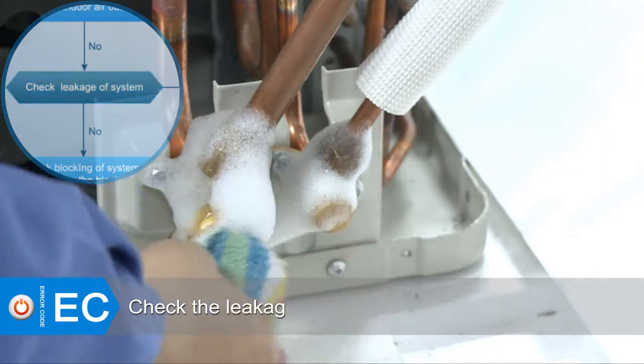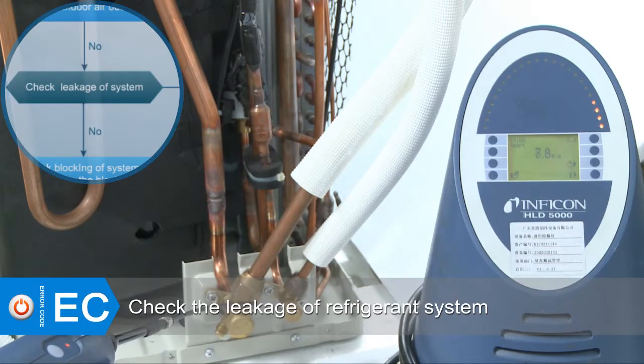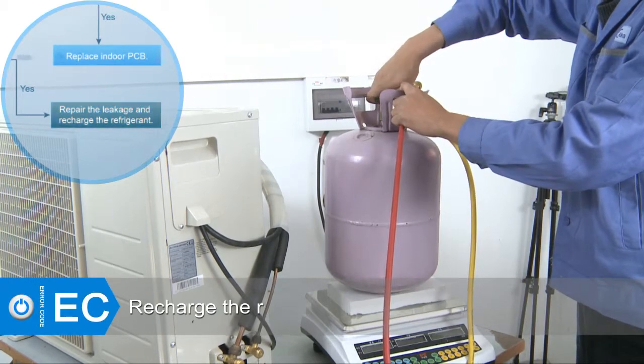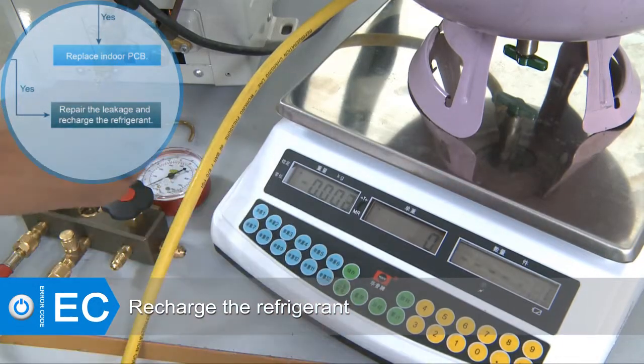If there is refrigerant oil on the joint, apply soapy water or leak detector to check if the system has any leakage. If there is any leakage in the system, repair the leakage, then vacuum and recharge the refrigerant.